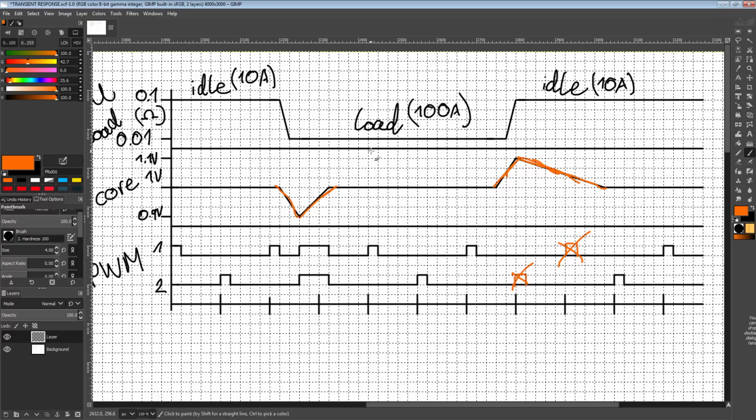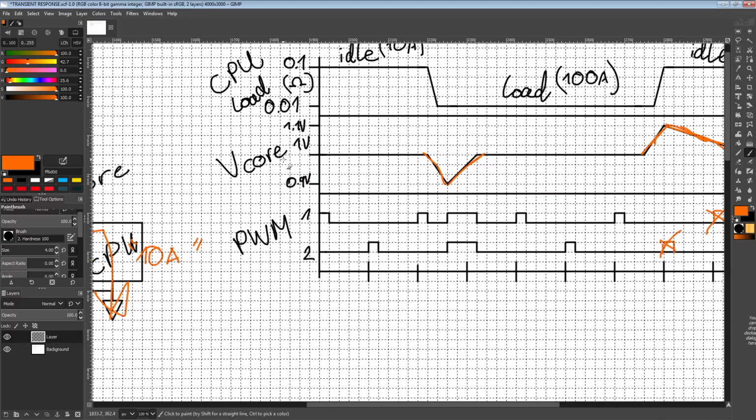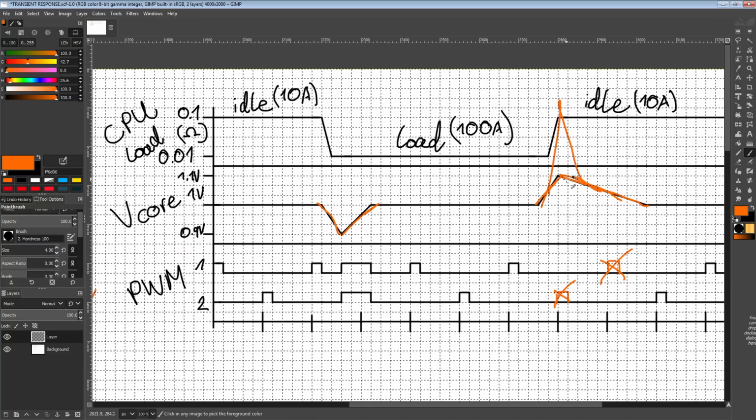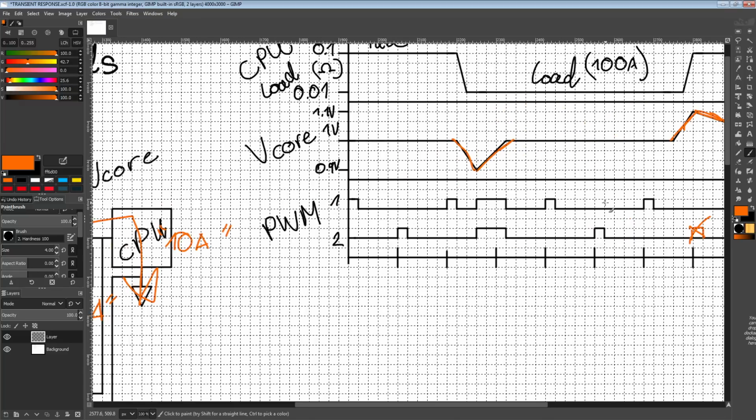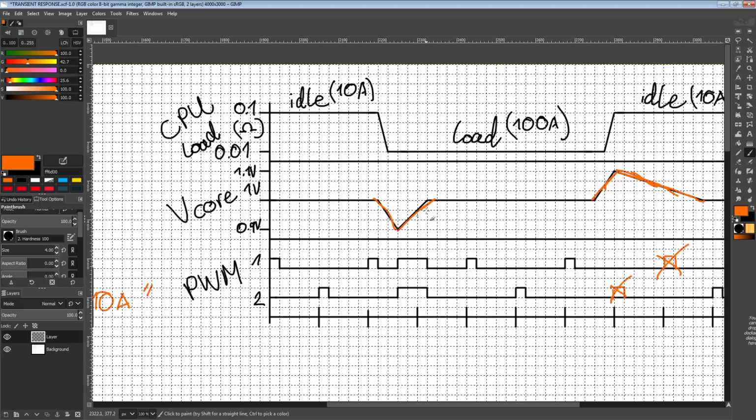It also depends on your absolute voltage levels, right? If you're at a very low voltage and your overshoot is really bad, the peak of that could still be relatively low relative to what's actually dangerous to the CPU. So, yeah, this is concerning from a reliability perspective for longevity. This right here, on the other hand, limits your maximum frequency.